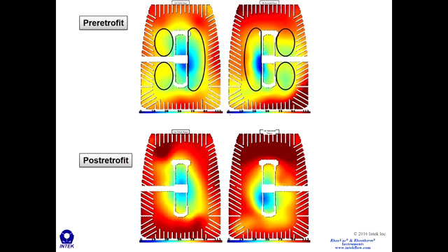You're probably familiar with this two bundle design here. So here's the pre-retrofit performance profile, for very low air in-leakage conditions. We've identified these airbound zones pre-retrofit in the 4 bundles here. And so what we did is we installed piping and baffles to extract this air without doing a retubing.